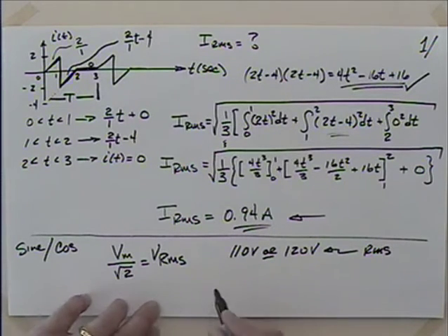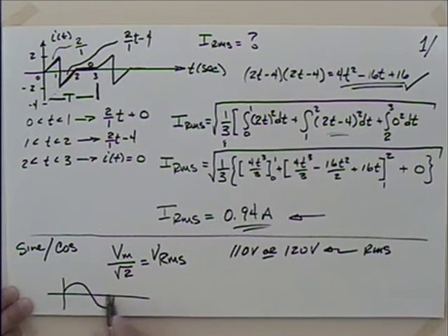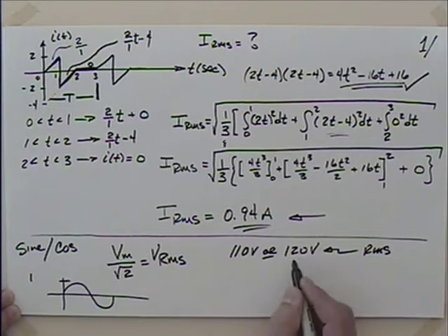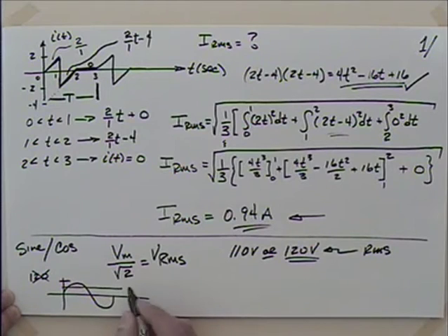So what's our peak value? Graphically, we thought we had a sine wave where the maximum was up here at 100, and let's take 120 just for easy figuring. So we thought this was up here at 120, and that's actually not true. What we have is the DC equivalent at 120, so this maximum value is quite a bit higher.